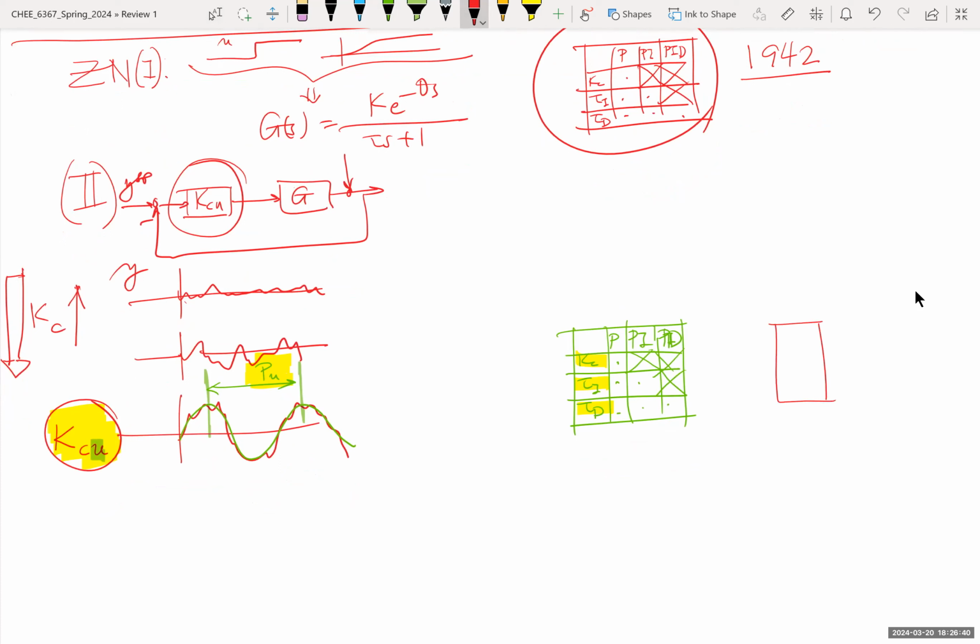So if you have the closed loop and this is y set point, and you look at the output, of course, there is an input here and there are disturbances. But if this is a step, the output will behave like this. And this here, which is the decay ratio, is 1/4. What's magic about 1/4? It's clean, small enough, fast enough response. They could have made it smaller, but then you might have to wait longer and you might have other issues.